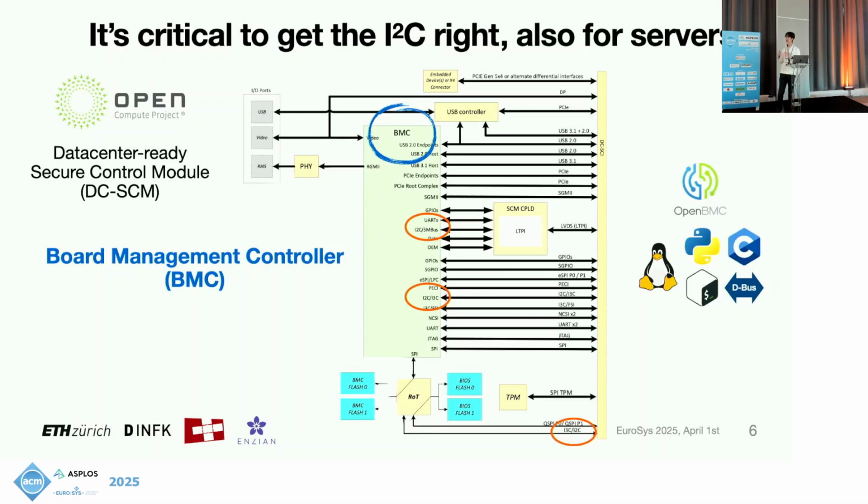It is a slightly more powerful standalone chip that runs its own firmware, but we see a similar level of hardware complexity in servers as well. The state-of-the-art firmware implementation for BMC is OpenBMC. Well, it is a Linux distribution. That means behind the scenes, there's another Linux managing your Linux machine.